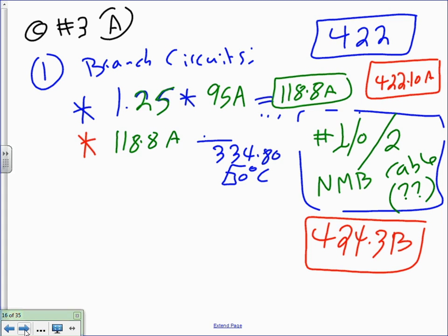When you go there, this will give you 60. You still need to go to Table 310.15(B)(16). This is going to be like Viking to you guys. Same thing, right? So what's 424.3(B)? It tells you heating equipment is sized based on continuous load, 1.25. Cool.